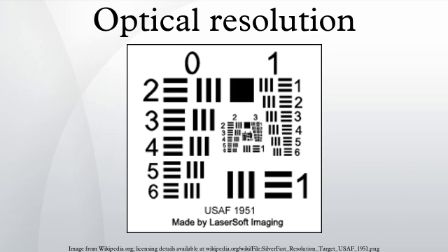System resolution. There are two methods by which to determine system resolution. The first is to perform a series of two-dimensional convolutions, first with the image and the lens, then the result of that procedure with the sensor, and so on through all of the components of the system. This is computationally expensive, and must be performed anew for each object to be imaged.